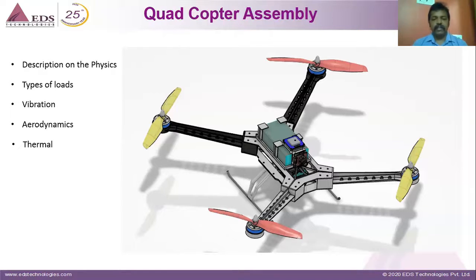Next thing is that when all these four motors rotate at variable RPM, of course, it would create a kind of vibration. These vibrations are caused because of the availability of air, velocity of air and density of air. All these things contribute to this vibration. And if the rotor is not good, or there's a fault in the bearing, or the payload is too much, or whatever it is, all these things will cause vibration.